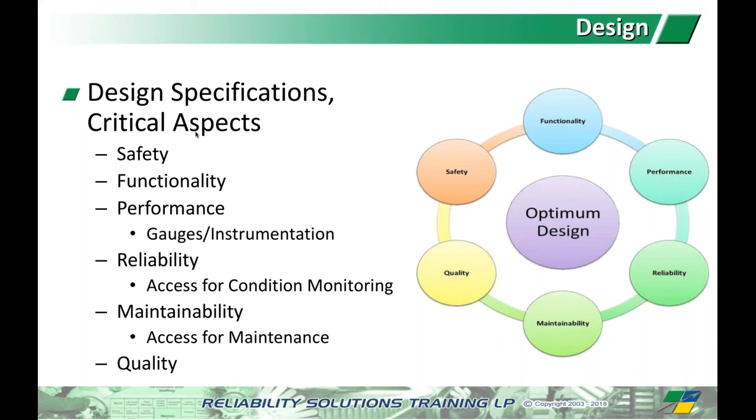Either they get left out or they get redlined as part of the bidding process because we want to get the cheapest bid. And when you do that, you end up with a system that you cannot really effectively and efficiently assess the performance. And all of you guys listening right now, think about how many fluid power systems you have in your facilities today that don't have gauges and instrumentation or the ability to assess their performance. It's an astounding number.